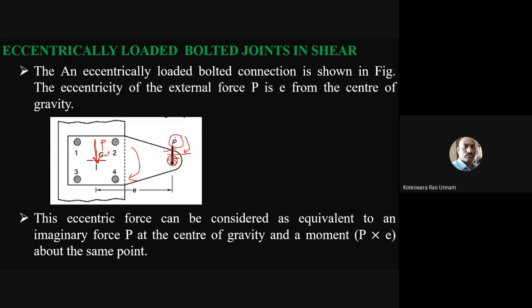So it will create a clockwise moment, given by load into perpendicular distance. Here this perpendicular distance we are taking as E. So the moment in the clockwise direction has a magnitude of P into E, where P is the applied load and E is the eccentricity.